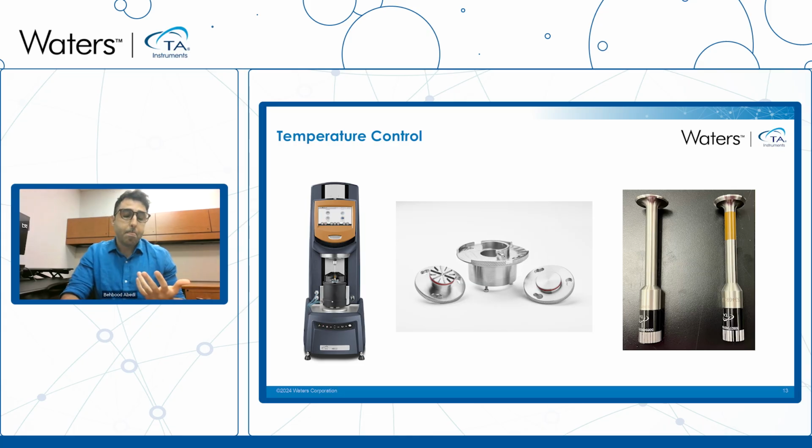And if you want to use temperature control, you see here at the right this geometry with heat break. We use the heat break because we don't want the upper part of the geometry to contribute to the temperature measurements. And you see these geometries have barcodes, so it's a smart swap. As you connect it to the rheometer, TRIOS reads the geometry, so everything for powder analysis pops up, and you can do it easily.